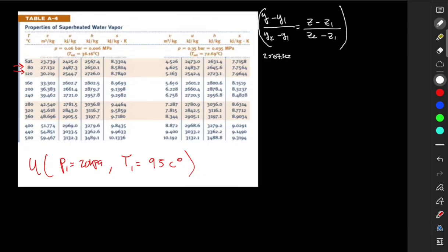So what I like to do first of all, when you're given pressure, is convert pressure to bar. Since I've been doing this for a while, I know that 100 kPa is 1 bar. So we just move this 1, 2. So it's roughly 0.20 bar. And as you can see, we do not have this in the tables. So we need to double interpolate.